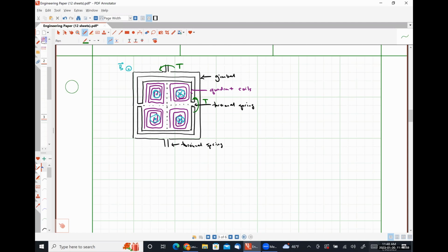So we have a two-axis scanner that uses the repulsive and attractive magnetic forces for its actuation, right? All working on whether or not the dipole moments are parallel with the field or anti-parallel with the external field, right? So this type of device literally has a permanent magnet affixed to the back of the substrate so that the entire mirror structure has a field all in one direction.